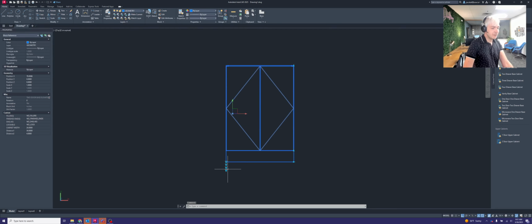And the last drop down that you see here is the addition of a lock. So lucky for you, in today's age, we don't actually need to use that grid quite as often that I was showing you in the last video for cabinet hardware. The lock locations that you see here in these blocks are already predetermined based on that detail grid that we looked at in the last video with the locks. So if you need a lock, it's as easy as saying, yes, I need a lock, or no lock. And if you do want a lock, it's already in the right location. If you don't want a lock, that's fine too. It's done, you don't need it.